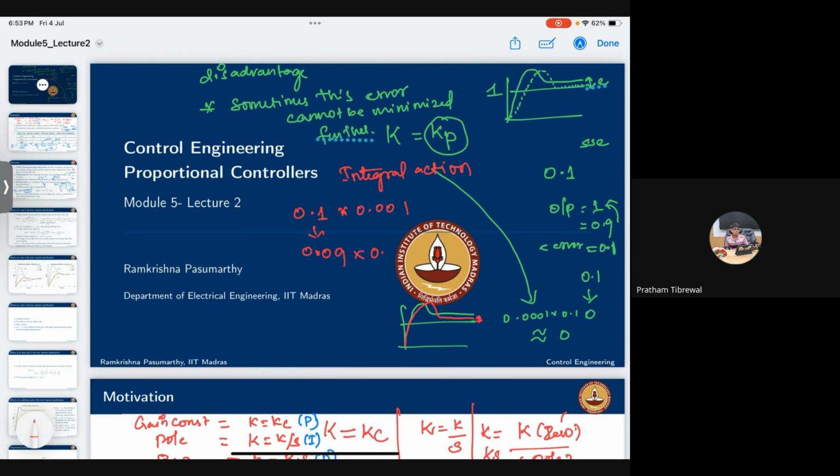If you again multiply this with 1, it will get further reduced. If I introduce this integral term, it will accumulate all the error we have achieved so far, and based on this it will change the gain. So you will achieve better stability of controlling the system when you introduce this integral. Coming to the differentiation part,